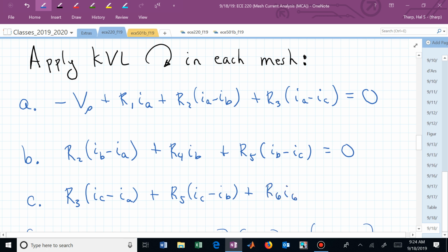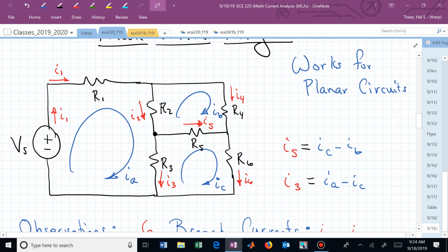No, I'll answer it. The question, I think, was consistent with what I was talking about with a messy mesh. If you now start saying, oh, I want I sub A to be clockwise, I want I sub B to be counterclockwise, I want I sub C, I don't know, flip a coin, counterclockwise, then this bookkeeping strategy that I just mentioned is out the window, is out the mesh.